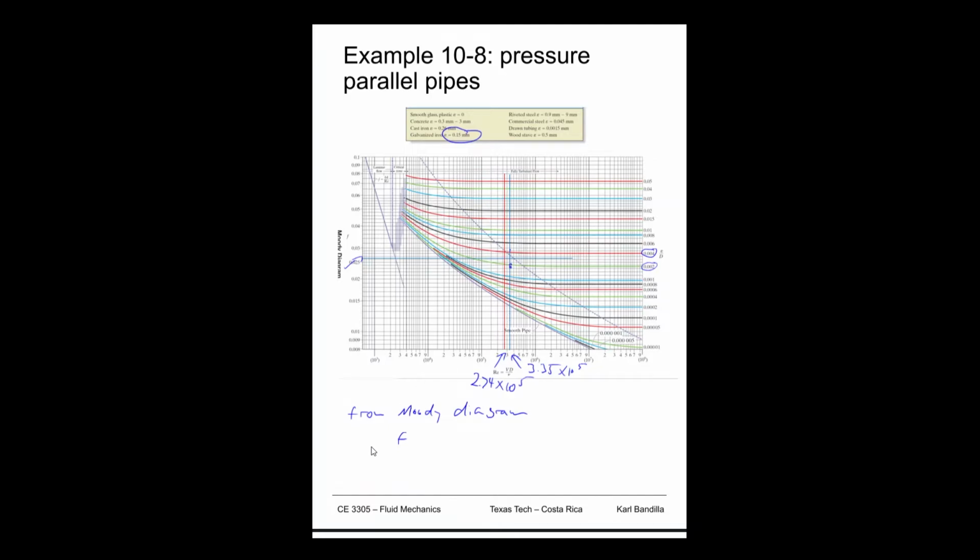The blue line is about halfway in between, so FB is equal to 0.0265, and if we do the same halfway point between here and there, that would be our C part, we can see that's exactly the same, right? So 0.0265. So FC is the same value. That's kind of because both of these lines get pretty flat in that area already.